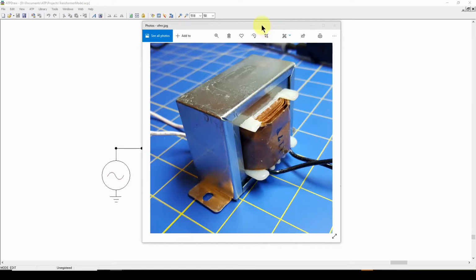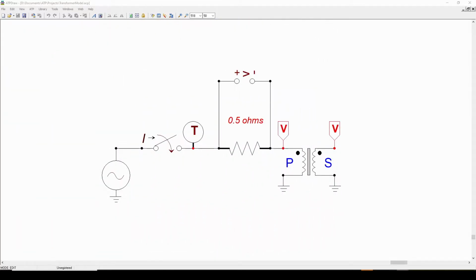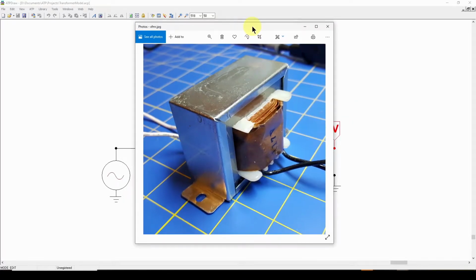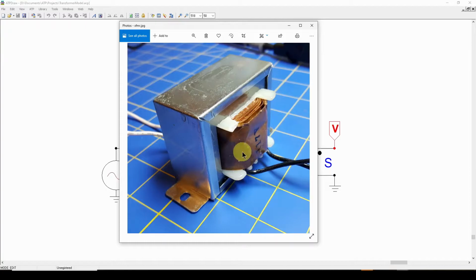And ultimately, we're looking at developing a model, a computer simulation model, like we showed in the previous video, where we model some of the characteristics of these transformers, such as their nonlinear characteristics. In other words, if you apply a voltage much higher than the design voltage, you can suddenly get a lot of current flowing even on an unloaded transformer. And you can get a lot of harmonics generated, and noise and heat and everything else. So we've been looking at developing a model for this transformer.